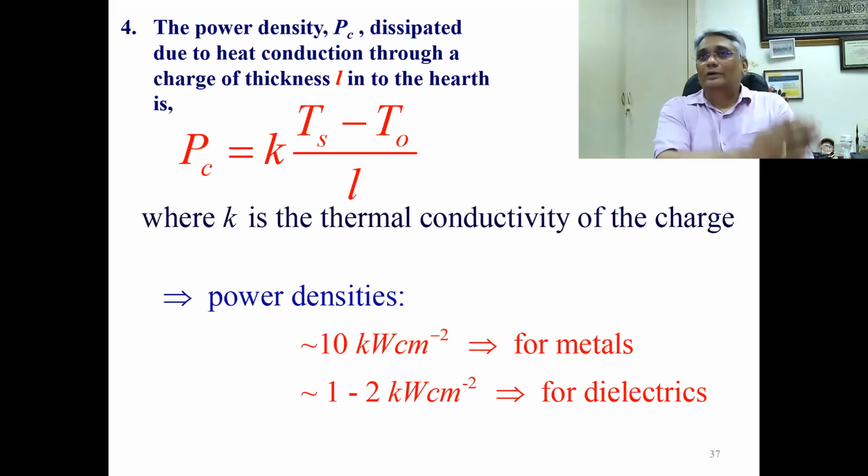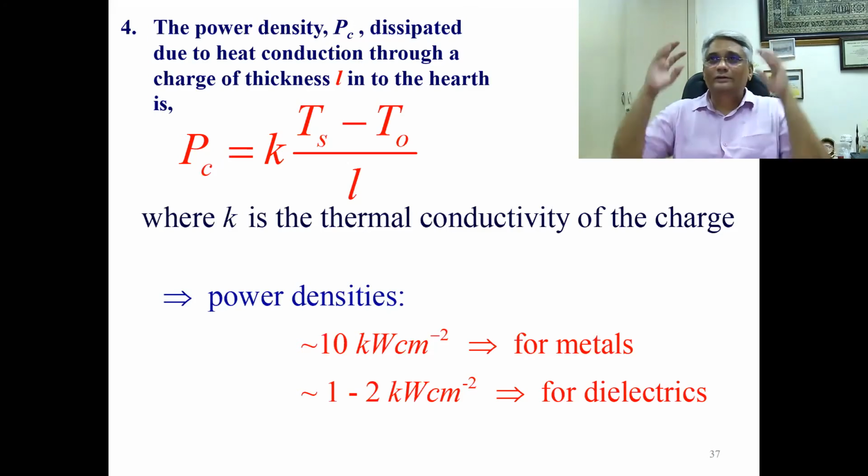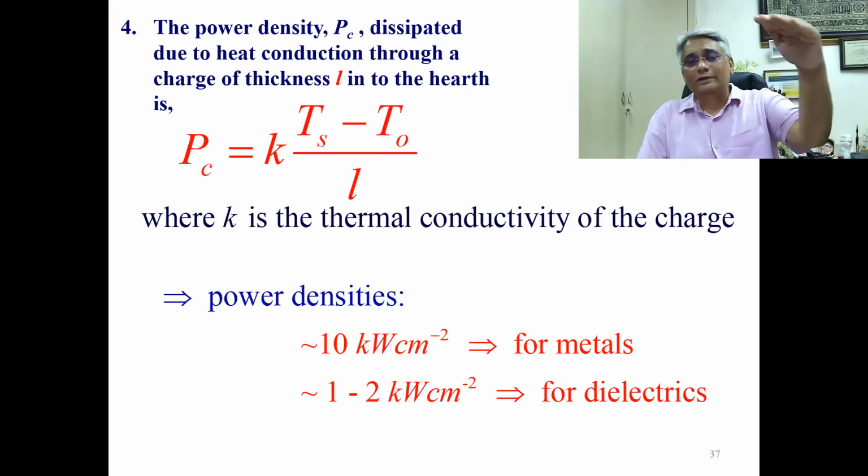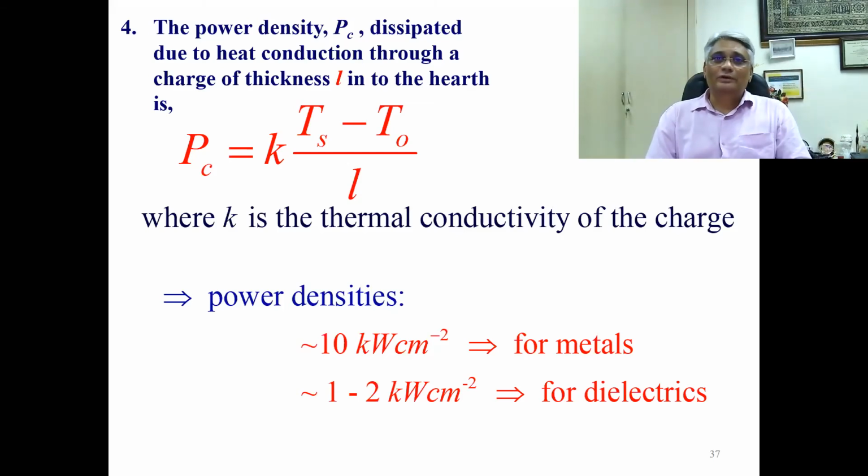So thermal evaporation, the first process that was invented long back, and a beautiful improvisation of that in order to avoid crucible contamination is the electron beam evaporation, where, of course, you have to take care of all these parameters to successfully deposit a layer of a single element or an alloy or multi-layers.